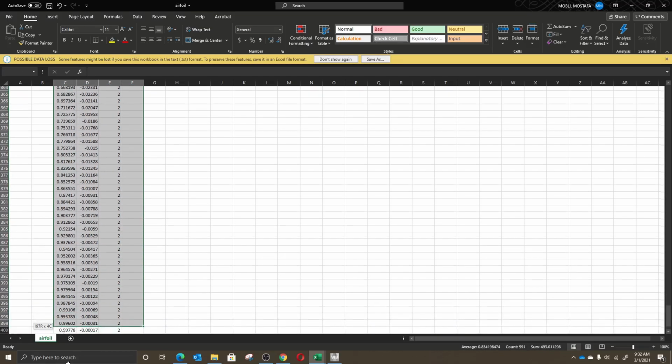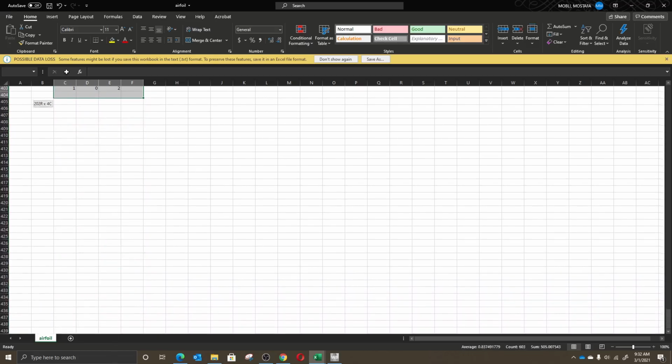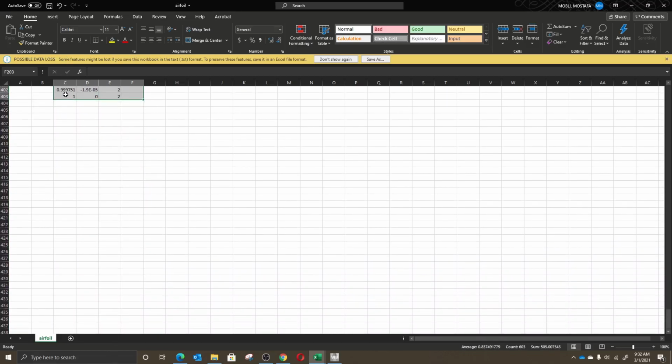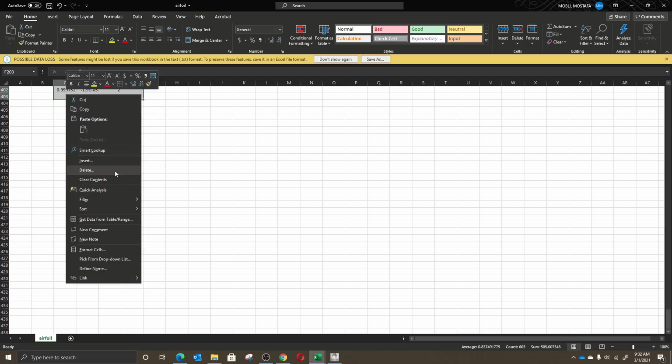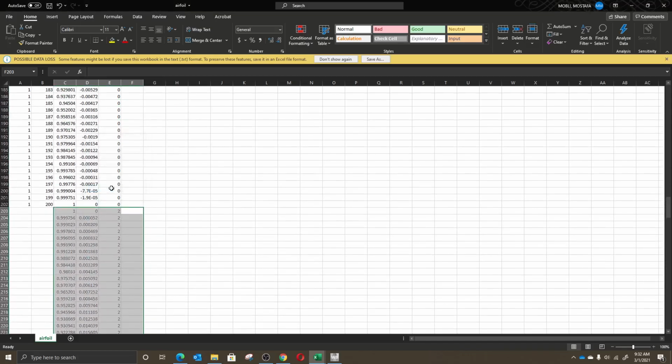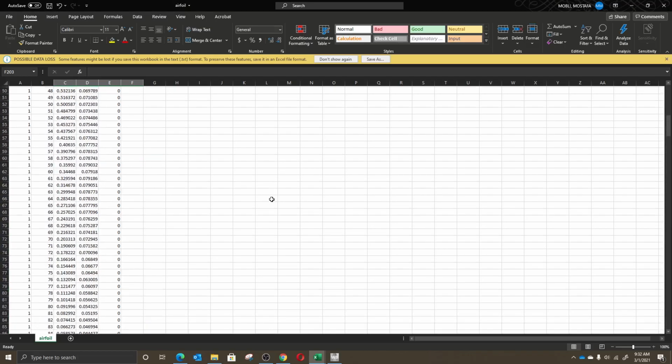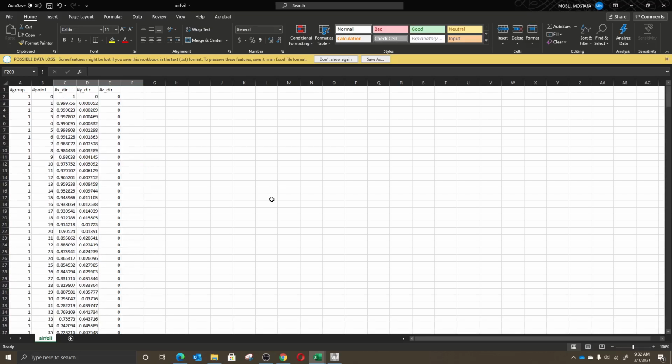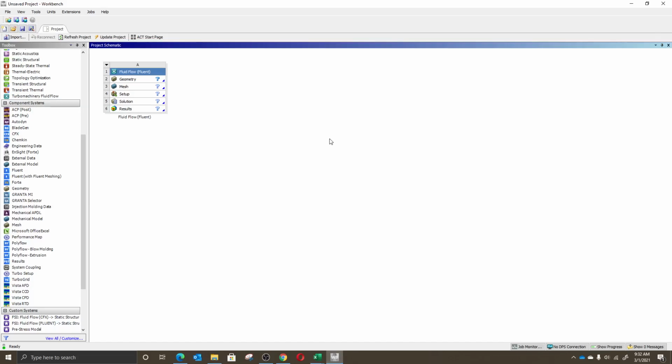But this part is a little harder, dealing with the data points, especially if you are dealing with a wing that has a variable chord, or it has a twist, or any type of non-rectangular wing. So in my opinion, it is better just to stick to the airfoil data points here, then do the rest of the analysis in the Ansys system.